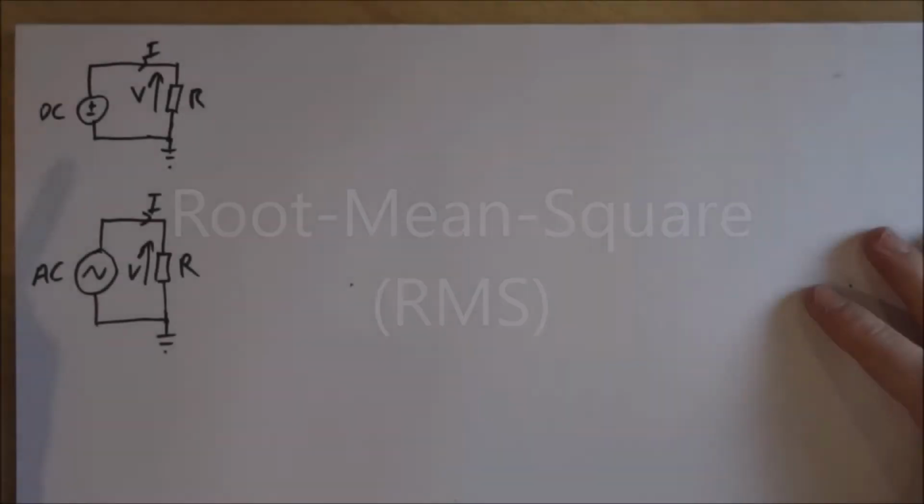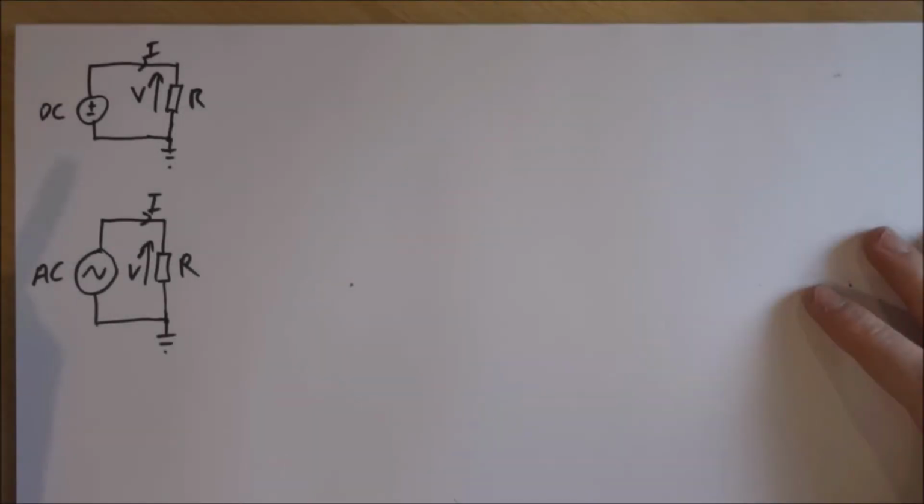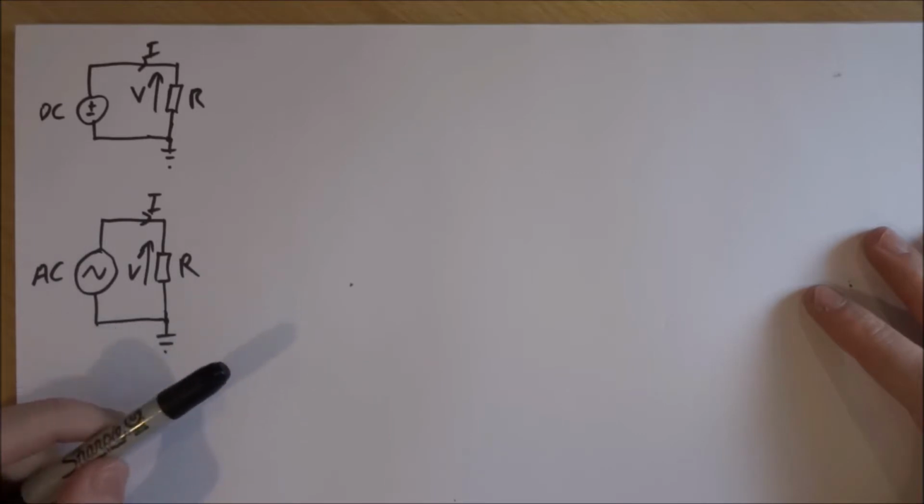In this mini tutorial, we will look at RMS and how it relates to voltage and power. RMS stands for the root mean square, and as the name suggests, we calculate the RMS value of a waveform by squaring it, taking the average, and then square rooting the final result. This will become more apparent after we derive the equation.